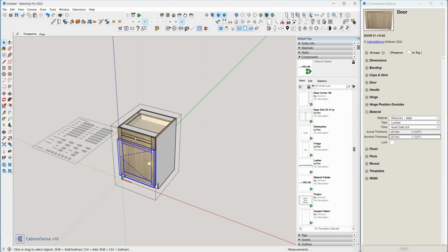So let's go back to our settings and let's change the way that we display our imperial format to be 4 decimal places. We'll click on the panel again and there's our 0.76. So what this allows you to do is if I wanted to go back and say, oh, you know what, we're going back to an unfinished end, we're going to flip back to the white, the actual thickness goes back to 0.75 because we haven't told it that the melamine white is any different than the nominal thickness.